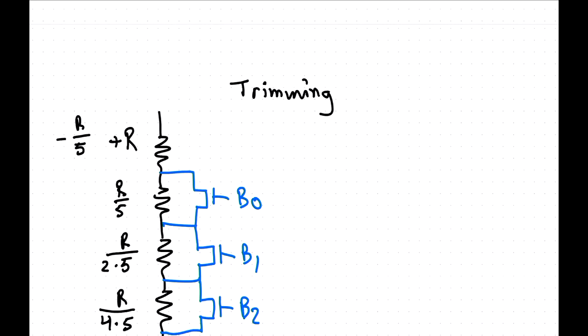Only when you boot your circuit up, then, depending on how they're stored, you switch them on and off. It could be pins on the chip, if you have enough pins, or else it could be in some non-volatile memory, or you can stream in calibration data. But it's normally something you do just once.